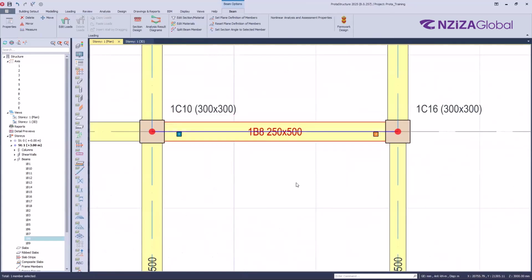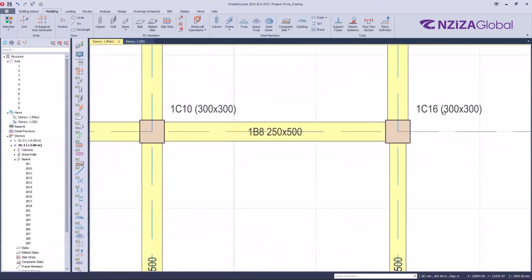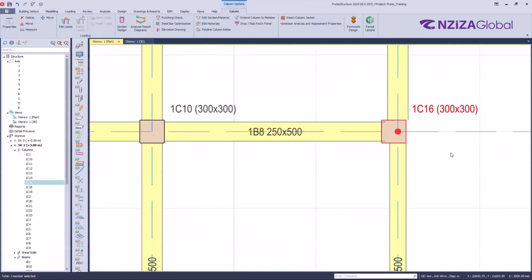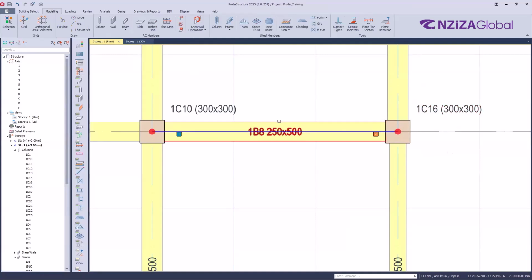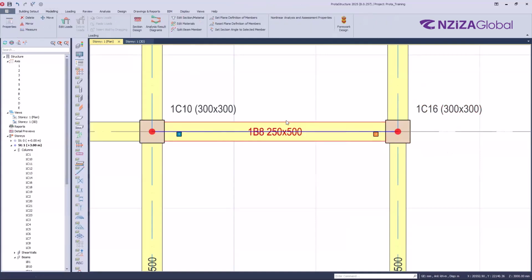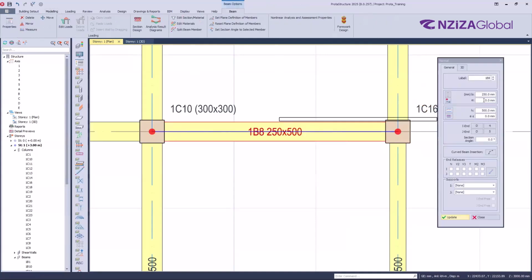As we saw, it is also applicable on the column. You can also apply eccentricity using the arrow key on your keyboard. So can you try it on your PC to see the difference of this E and EZ before I go on with the remaining settings of the beam?